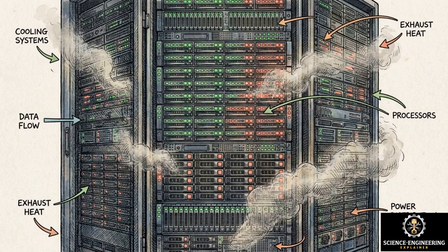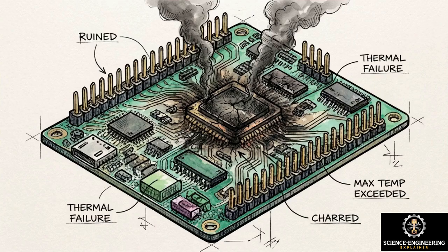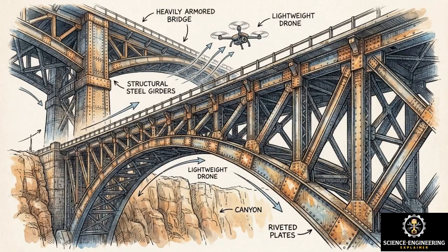It requires a robust operating system, usually Linux, just to run the background network. Because of this heavy footprint, trying to run ROS on a simple microcontroller or a basic hobbyist board will completely overwhelm the processor. ROS solves the fragmentation of robot programming, but it acts as a resource-hungry bridge that is only justified when you are building complex, multi-sensor systems.